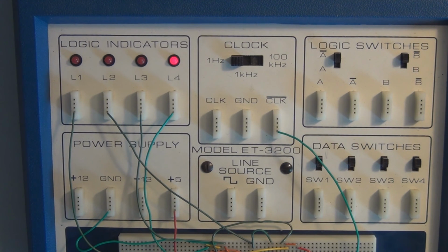And then we've introduced a JK flip-flop, which does away with the ambiguous state that the Set-Clear flip-flop has, and we have a new toggle mode where if we set J and K equal to 1, the flip-flop will toggle, Q output will toggle from 0 to 1 or 1 to 0 on the leading edge or the falling edge of a clock pulse.